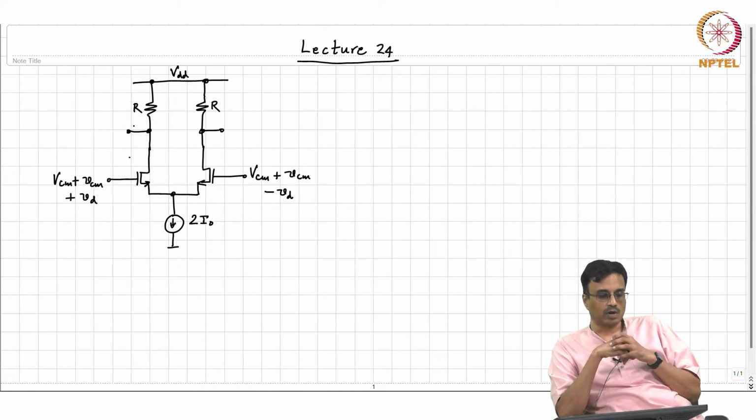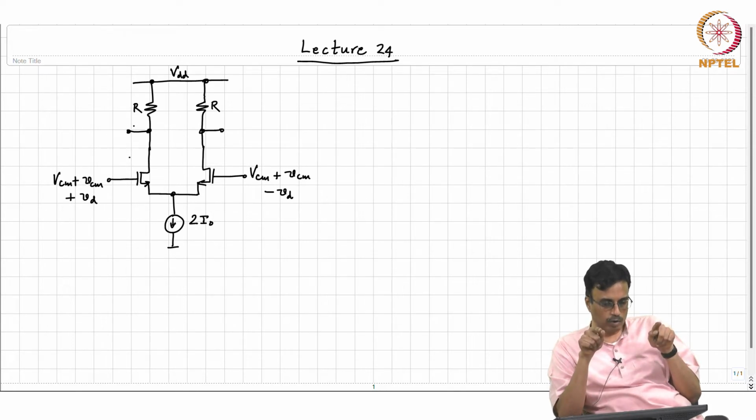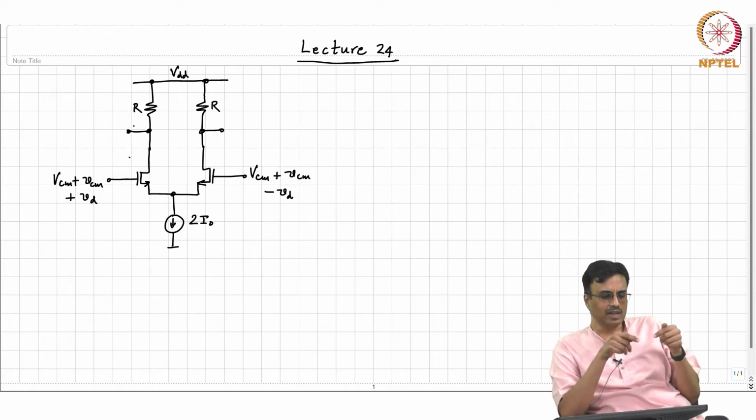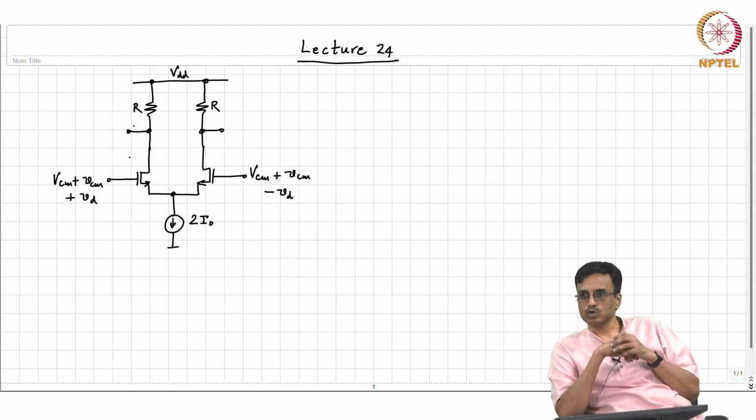So, as far as the negative feedback loop is concerned, its job is not to worry about what the two voltages are, V in and V out. Its job is only to look at the difference between the two, which is V out times F and V in, and then do whatever it takes to keep that difference equal to 0.